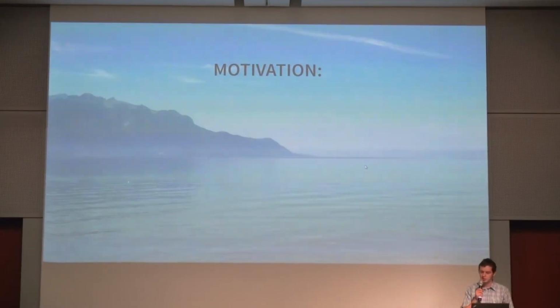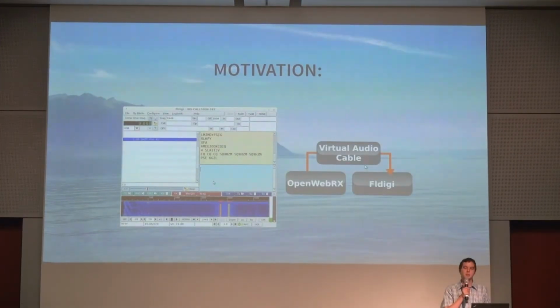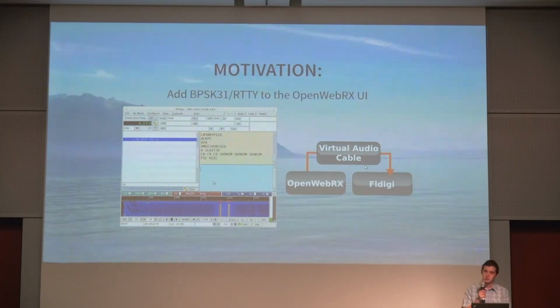That, it did not support digital modes until recently. So you had to use digital modem software like Fldigi and connect it through virtual audio cable, which is quite an effort for beginner users. And also OpenWebRX uses lossy audio compression between the server and the client, so it's actually not that good for Fldigi. And to solve that, the demodulator needs to be put at the server side and also has to be integrated in the UI. So that was one motivation.